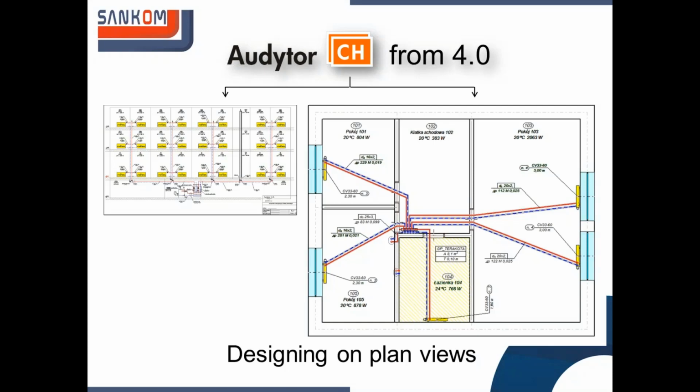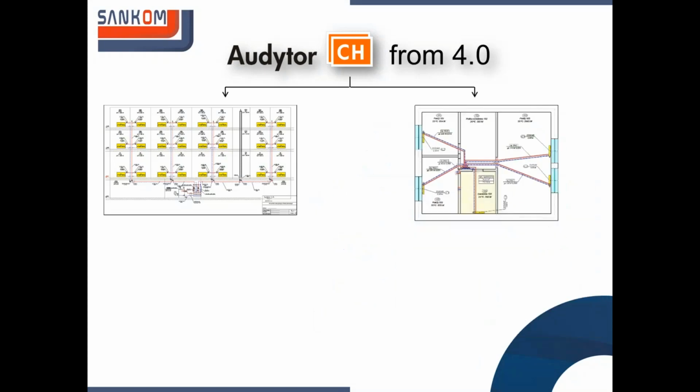So we obtain a full 3D model of the building, and the program can take the lengths of all the pipes, both vertical and horizontal. So you don't have to enter any lengths of pipes manually. You save a lot of time, and you also obtain plan views later on that are useful for the constructor. But generally, you have two methods to choose from.